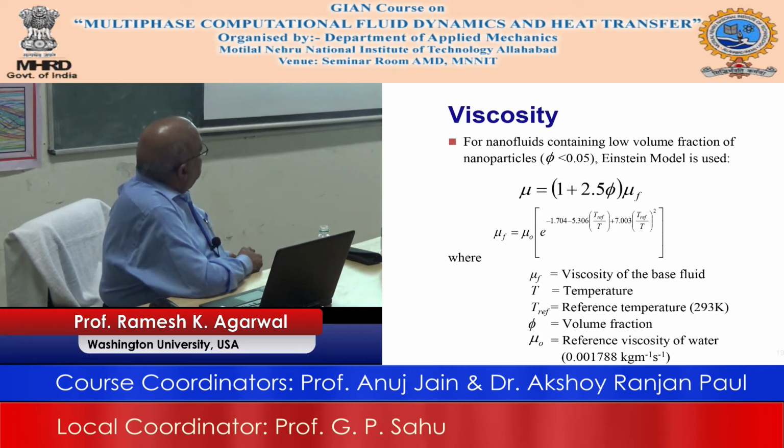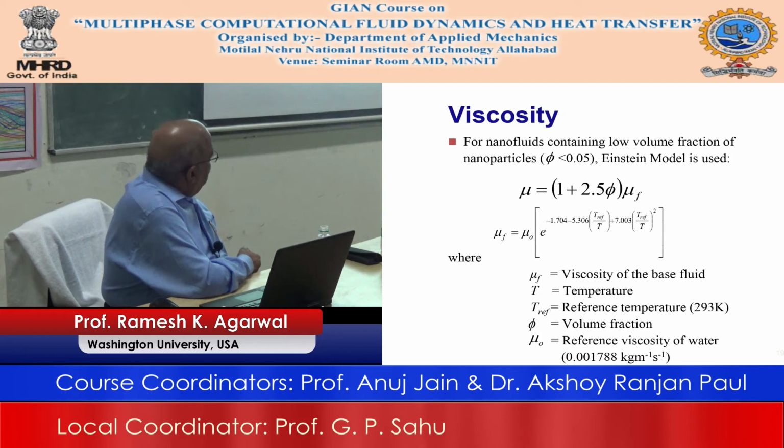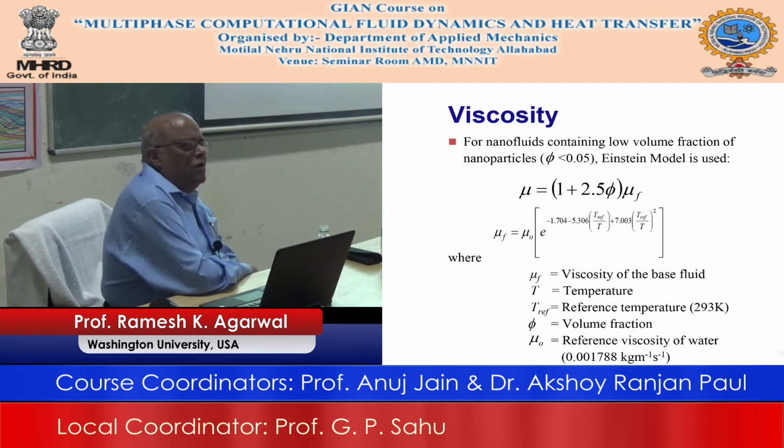And then, of course, this is what is called a Brinkman formula, which people prefer, and again you have a little more complication in it. Okay. So these are all the properties, and then beta is the thermal coefficient of expansion, which we know is a function of temperature. And of course, there are correlations that they can fix in the temperature range that you are interested in. So this is about 20 degrees centigrade to maybe, I don't know, 50 degrees centigrade.